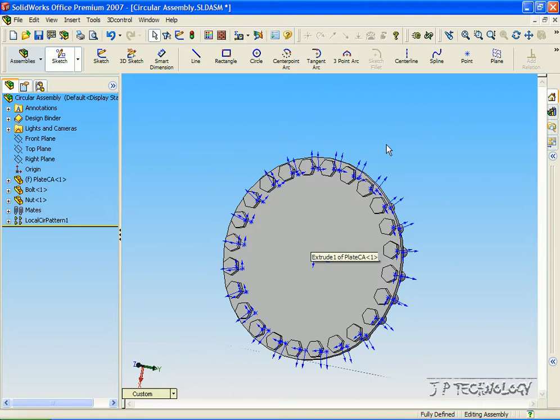Now, you'd use this for, an example would be if you have a suspension system and you have a limited area that you want the suspension system to be in and work within, you can create an envelope or an area for the suspension system to work in. Then you can put it with the assembly, and you can see physically if all the components are inside the envelope and if they're working in the confined area.